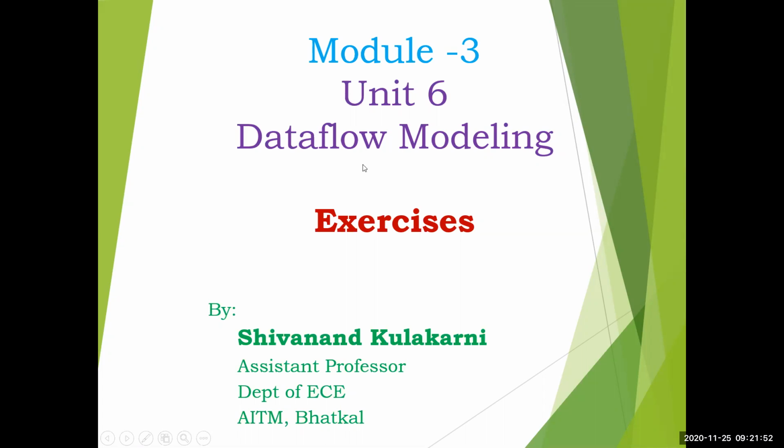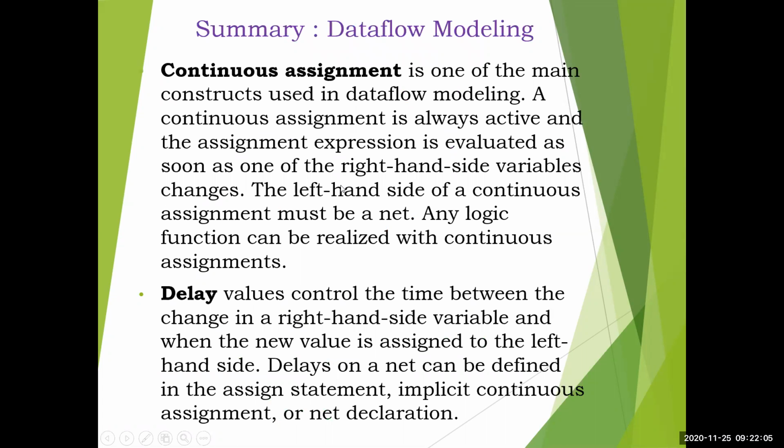Before that, we'll first summarize what we have learned so far in data flow modeling over the last 6 to 8 videos, and then we'll look at the exercises. First, continuous assignment is one of the main constructs used in data flow modeling. The keyword is assign.